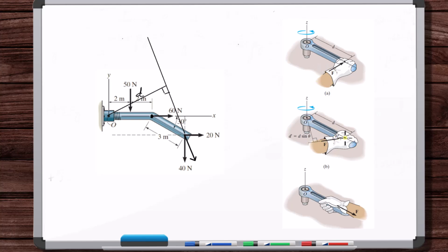Okay, now if we look here, this is a planar problem. So you can calculate the actual moment arm in the plane, the perpendicular distance, perpendicular to the line of action of the force, and do F times D. But more commonly, you're just going to resolve this force into components, and then say, okay, this component times D, and this component doesn't have a moment about O.